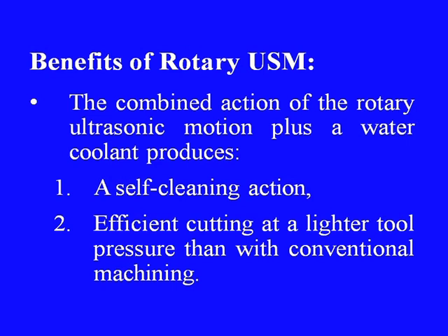Let us see the benefits of rotary USM. The combined action of rotary ultrasonic motion plus a water coolant produces a self-cleaning action, because the tool head is rotating and gets washed continuously, and an efficient cutting at a higher tool pressure than with conventional machining.